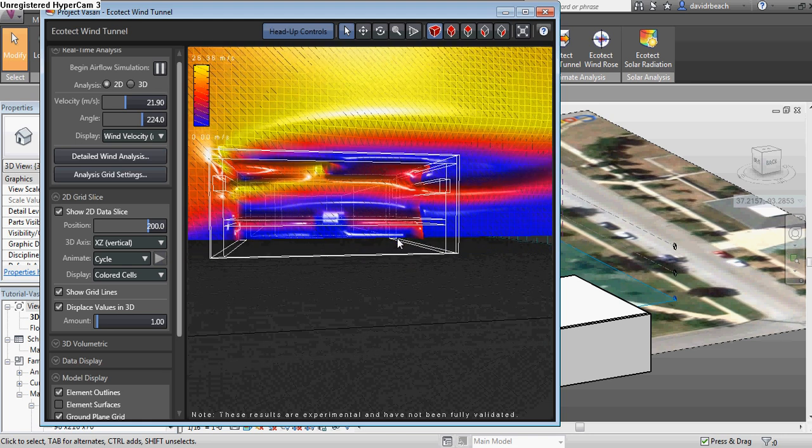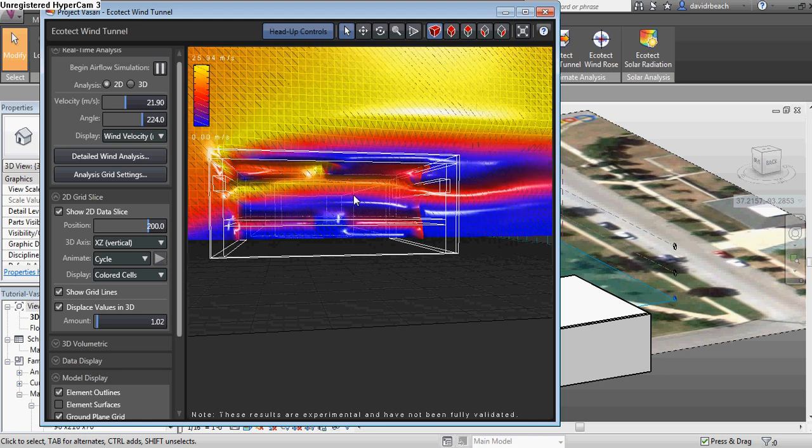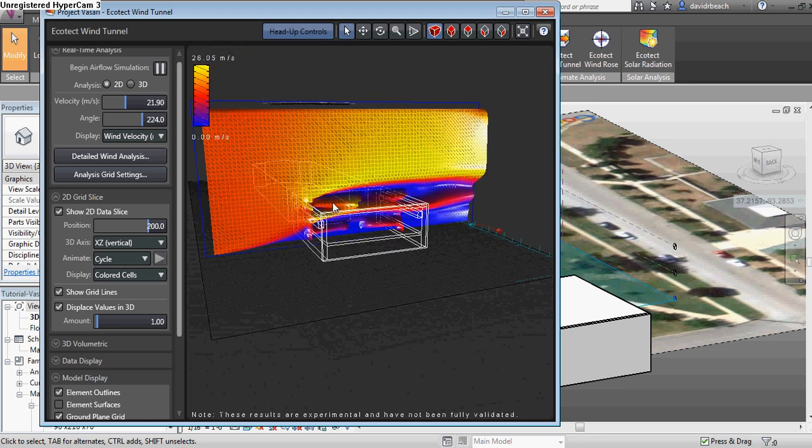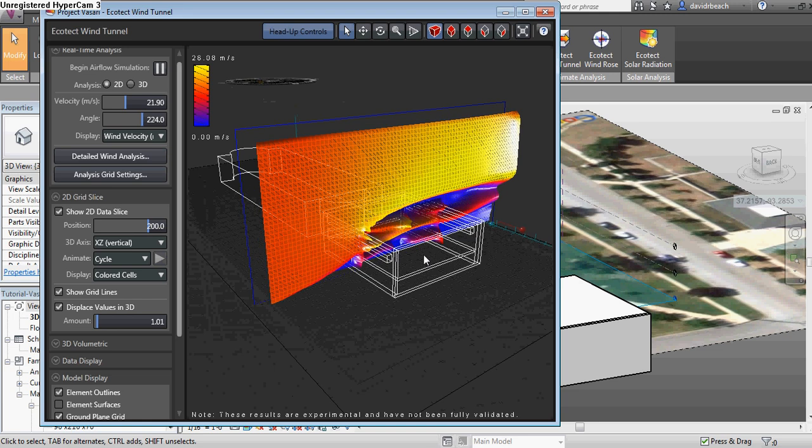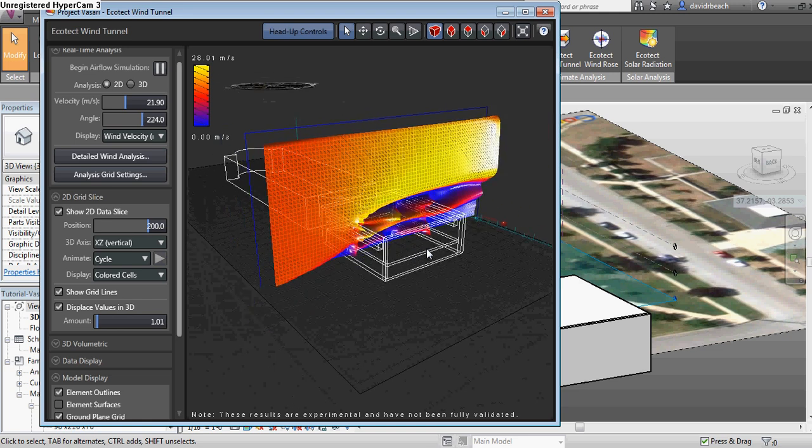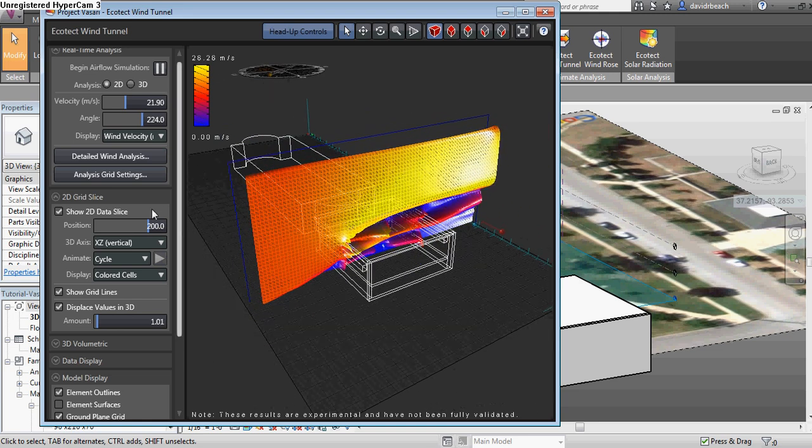And we can start to see some interesting things. First of all, as wind is passing through, we know we're occupying largely the space below the windows. And you can see that any cross ventilation we do have, unfortunately, stays only up high. In fact, it even sort of arcs up just a little bit, keeping us comfortably out of any potential wind movement, other than perhaps it having the opportunity to pull a little bit of the hot air off of us as it rises. So again, not the most productive in terms of cross-ventilating a design.